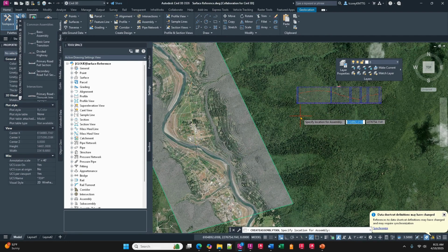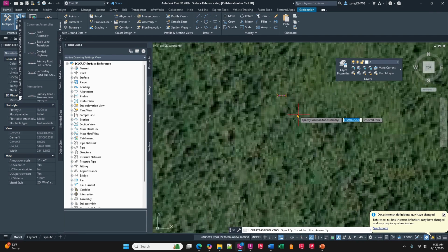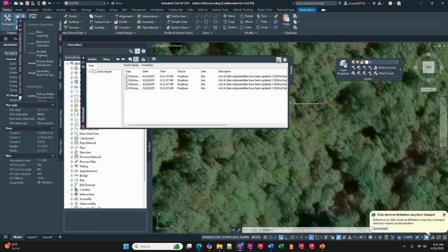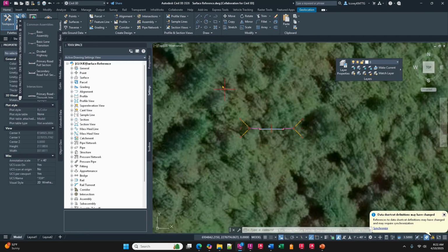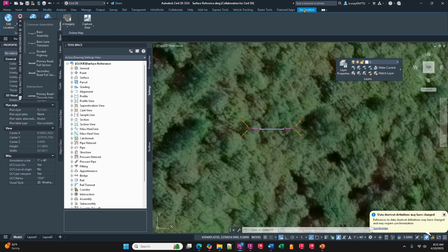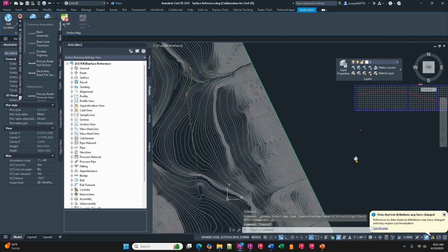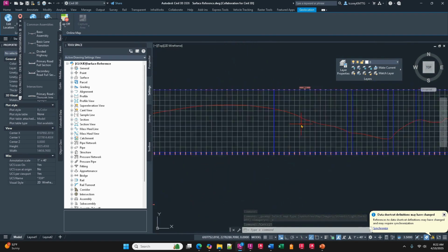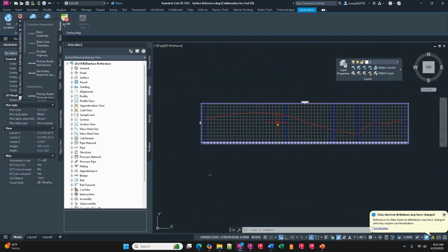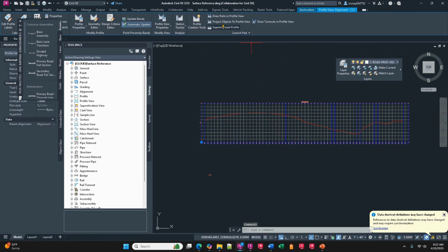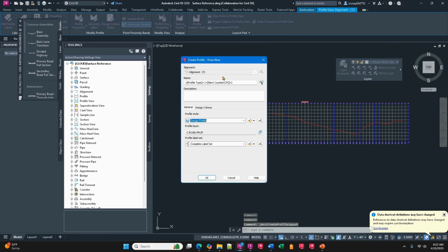So where am I putting that? I'll stick it here. So that's my assembly. Okay. I can turn off my map now. Map off. So I'm ready to make a corridor here. Let me do a finished ground profile. So I'll pick the profile view, tell it profile creation tools, and names, fine, layout.